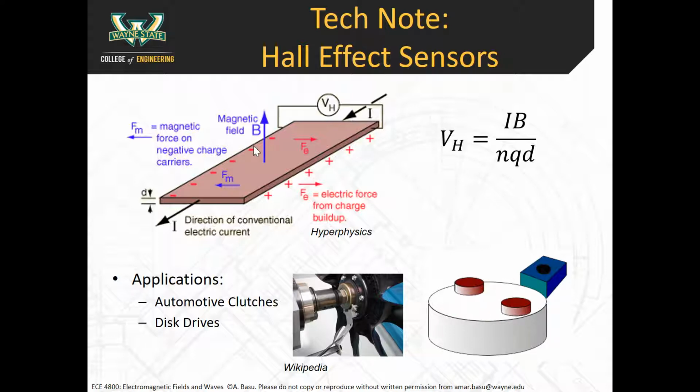By applying this voltage across here, you generated a current. You generated a moving charge. Now, suppose you also have a magnetic field B here. Does anyone remember how to apply the right-hand rule with electrons? Just negative with that one. So it's the opposite direction. This is how I like to do it: just apply the right-hand rule as you normally do, but negate the direction of the Lorentz force.